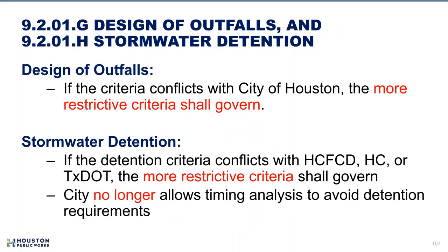A lot of people asked, if we design the outfall directly into Harris County, do we not have to follow the city's design requirements? The answer is no. Even if you are outfalling into Harris County, TxDOT, Harris County Flood Control, or any other agency, we still have language saying the more restrictive criteria shall govern. So look at which one is more restrictive, and that's what you should use.